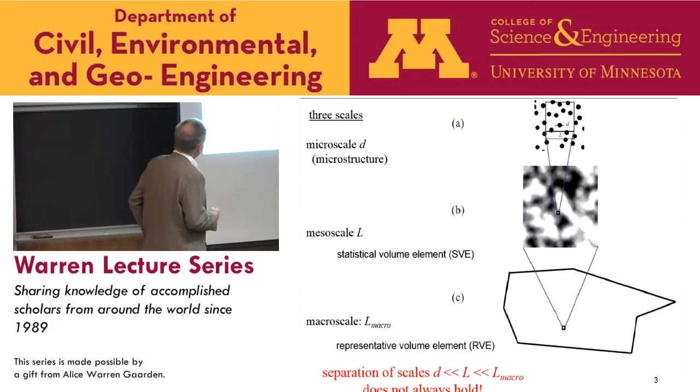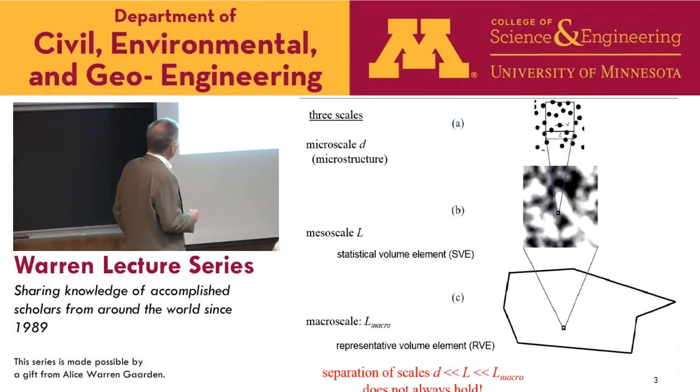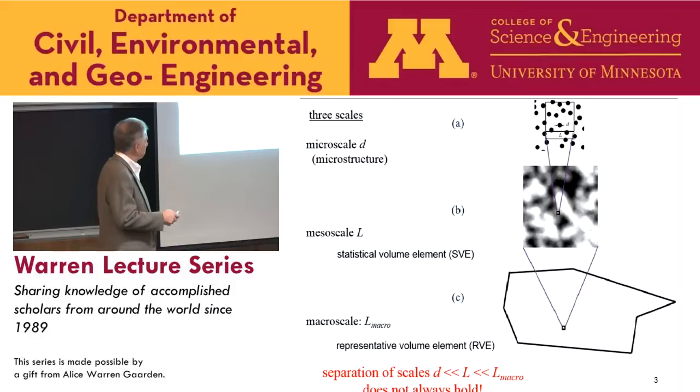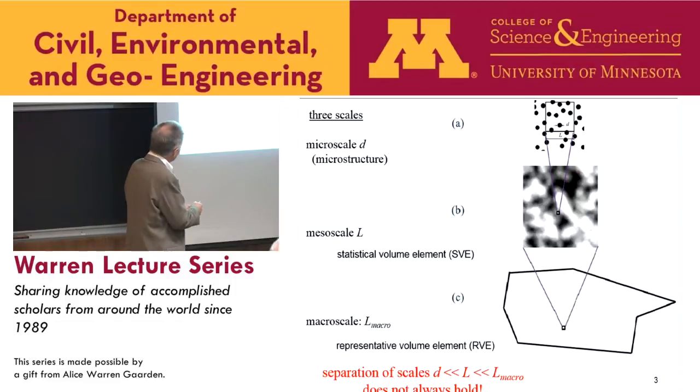So I'm looking at homogenization of microstructure, actually a single realization, so everything is deterministic, to a continuum-type random field. Mesoscale, so meso from Greek meso means intermediate. And if this window is not large enough, then we'll have fluctuations seen here. But if the window is large enough, then we won't see those fluctuations. Depending on the situation, perhaps here we'll have to deal with a random field of, say, material moduli as opposed to a constant, non-random field.